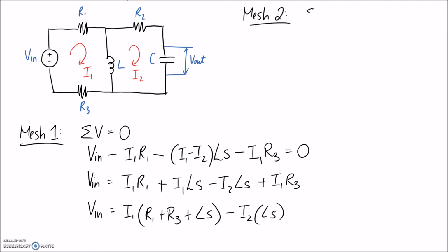So again, the equation that we need to solve is that the sum of the voltages around the mesh is equal to 0. So I might start in this bottom corner again. This time everything's going to be a drop in this one because we have nothing coming in. So what I might do is just treat everything as positive, make it easier.